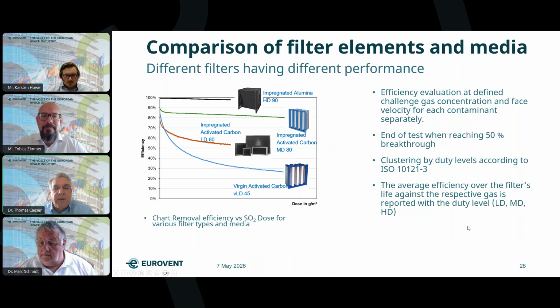As Tobias has also shown, here are some more examples. I showed in the first slide that the same filter acts very differently to different gases. In the same way, different filters act very differently to the same type of gas, depending on the adsorbent and on the chemical impregnations on the filter. So there is a wide range of different filters that can be applied to different gases.